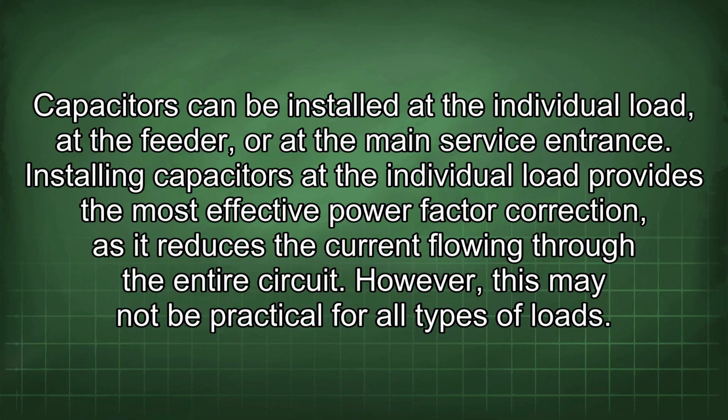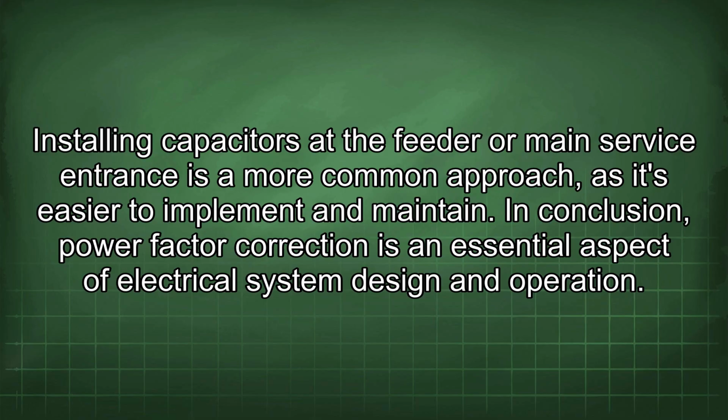However, this may not be practical for all types of loads. Installing capacitors at the feeder or main service entrance is a more common approach, as it's easier to implement and maintain. In conclusion, power factor correction is an essential aspect of electrical system design and operation.